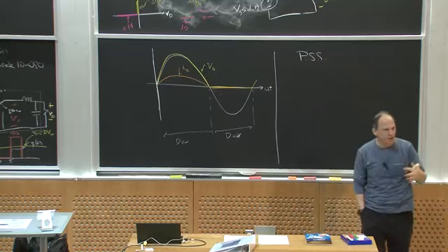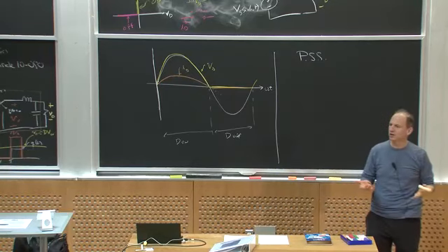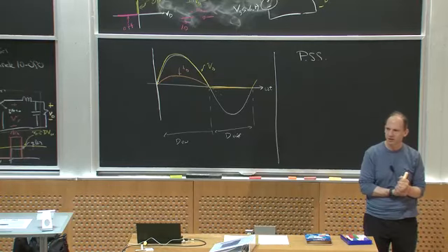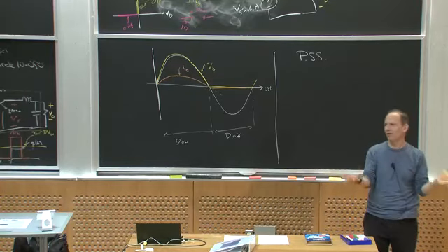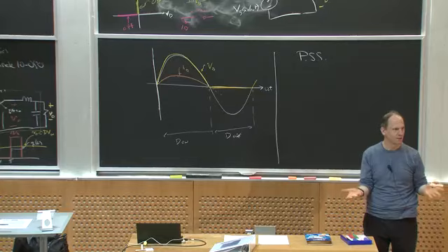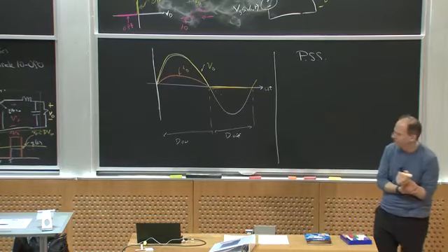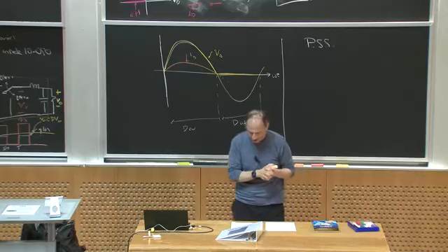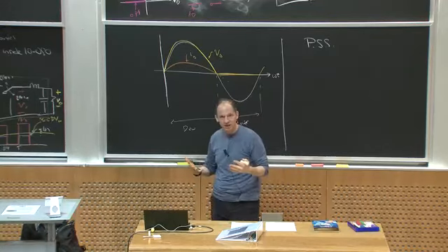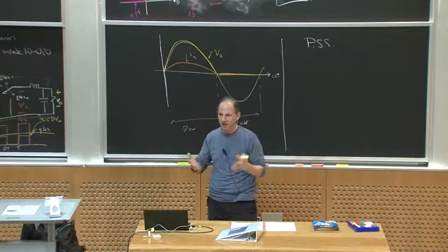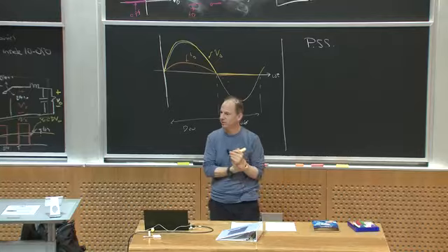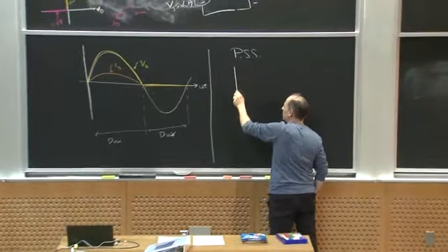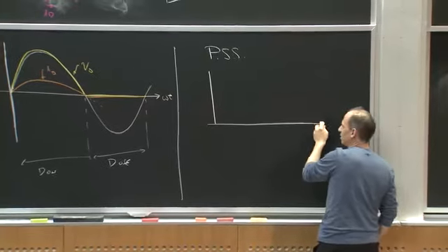Now, the notion of periodic steady state is a little bit like the notion of sinusoidal steady state, which you would have studied in linear circuits, except that we don't typically have all our waveforms being sinusoidal, right, because we have some kind of nonlinear circuit going on. But it's a related concept. And the idea is this. We're operating cyclically. Eventually, what we expect is for every cycle, the circuit to do the same thing. So periodic steady state operation is something like this.